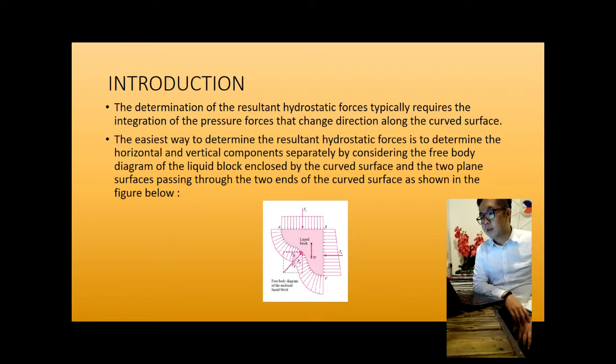So the easy way to determine the resultant force is to determine the horizontal and vertical components separately by considering the free body diagram of the liquid block enclosed by the curved surface and the two plane surfaces passing through the two ends of the curved surface, as shown in the figure.